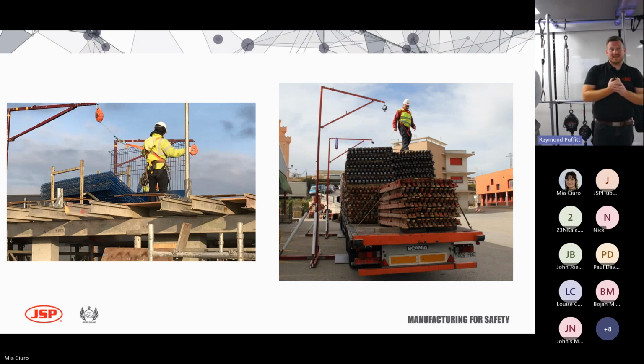I've got a couple of examples here of guys using standard fall arrest blocks. The guy on the roof has actually got an extension lanyard connected to that. His block's not high enough. We can already see that's going to be above 40 degrees once he wants to get to the edge of the roof. Once he goes over it, he's going to bring sharp edge into play because his block is already above the 40 degrees recommended for fall arrest blocks. He's also got the extension lanyard, which will cause extra force.